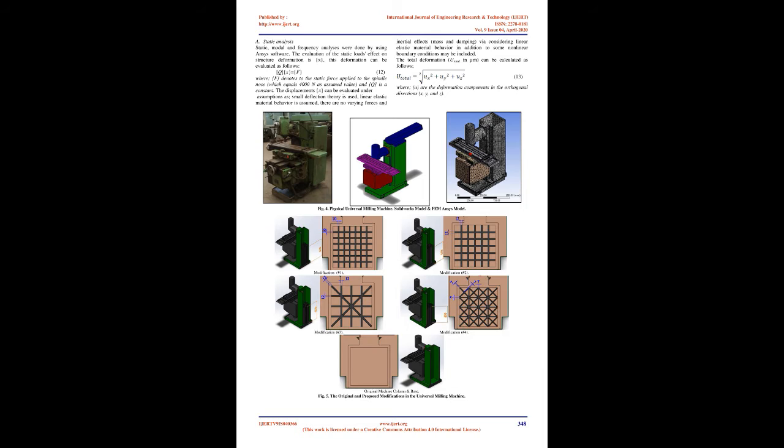Case study of cutting speed V equals 30,480 mm/min, tool diameter D equals 101.6 mm, number of teeth of the cutter NT equals 8, width of cut B equals 67.3 mm, depth of cut A equals 4.064 mm and feed rate S equals 152.4 mm/min, is used in this article.